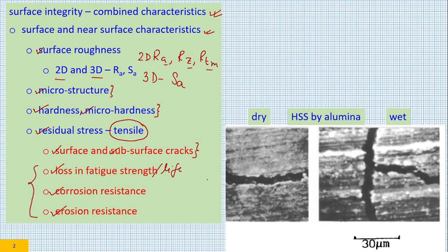And if you have a very large amount of tensile residual stress, then the fatigue life would be a problem. Most of the time, in mechanical engineering, if it is a power transmission shaft which is subjected to both bending moment and shear stress, and its fatigue life is compromised because of high tensile residual stress upon grinding, then that grinding process would not be acceptable.